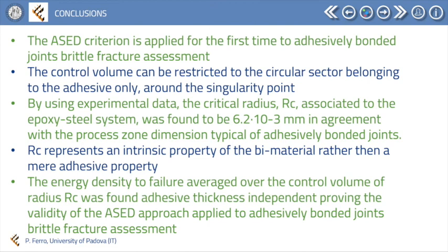And finally, using experimental data found in literature, the energy density to failure averaged over the control volume of radius RC was found adhesive thickness independent, proving the validity of the average energy density approach applied to adhesively bonded joint brittle fracture assessment.